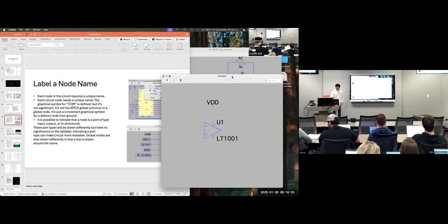Okay. Another nice thing about node names is that we can treat node names like variables. Like in computer science, we have the variable x equals whatever, and then we can reference x again. In SPICE circuits, I can have a node name, let's say VDD, and then instead of drawing a wire from the VDD of U1 all the way to some power source, I can actually disconnect it virtually and then reinitiate it using VDD again. I'll show what that means right now.